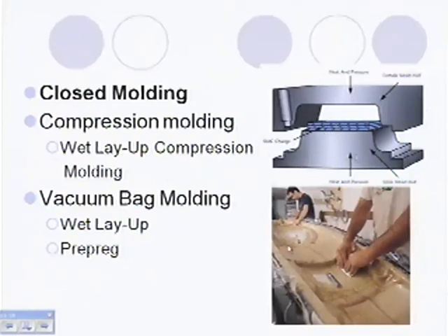So that's compression molding. The dies are very expensive to make, and most of our work is custom, so it would be too expensive to make this for each individual patient. So this is done more for mass production, where you're trying to make a few thousand of a part.